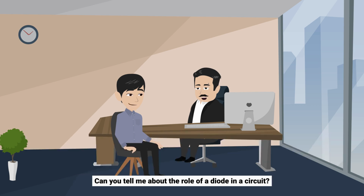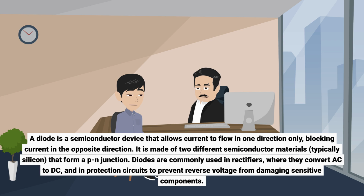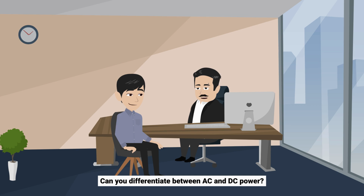Can you tell me about the role of a diode in a circuit? A diode is a semiconductor device that allows current to flow in one direction only, blocking current in the opposite direction. It is made of two different semiconductor materials, typically silicon, that form a p-n junction. Diodes are commonly used in rectifiers, where they convert AC to DC, and in protection circuits to prevent reverse voltage from damaging sensitive components.